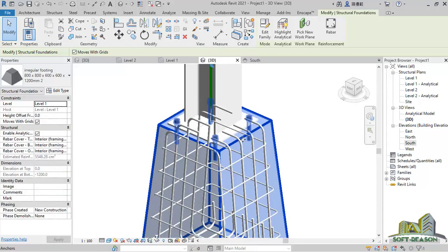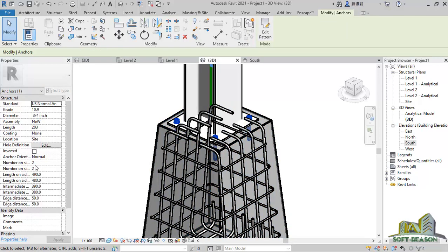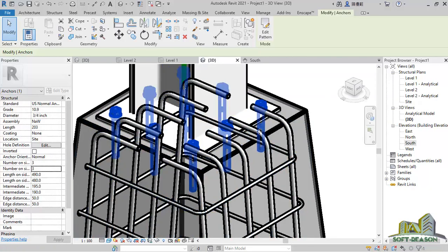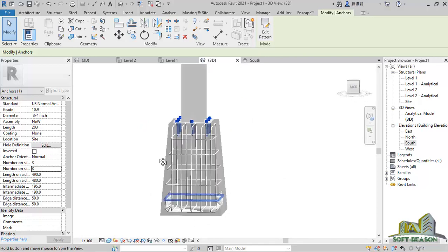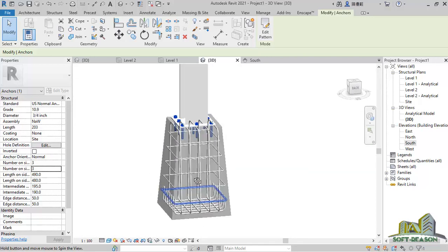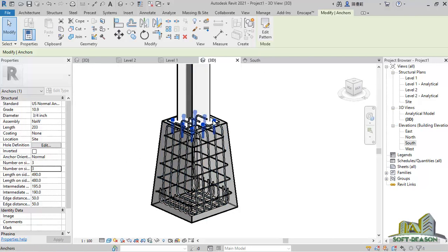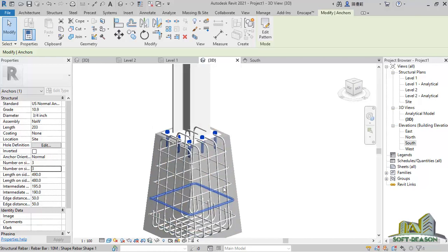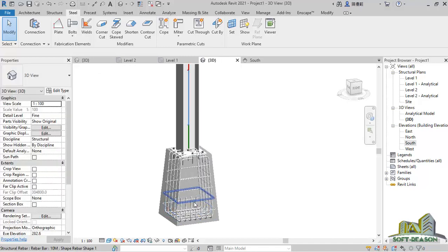Alright, so after which you can select the bolt again, depending on the number of bolts you want to have. Now you're having 2 in both sides, you can make it 3, and here also 3. So you can see an additional 1 bolt added there. Okay, so this is how you actually place your bolt, plate, and as well as the stanchion. Okay, so you see what we are having now. So you can just place your design just like this.